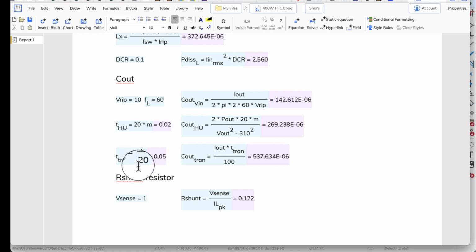Now, if I have a bunch of 20 hertz things, that's okay because they're going to be averaged over, and you're going to be taking care of one big old gigantic 20 hertz thump. And I don't want to interrupt that. So I want my second stage to ride through that. So I need a capacitor of about 527 microfarad.